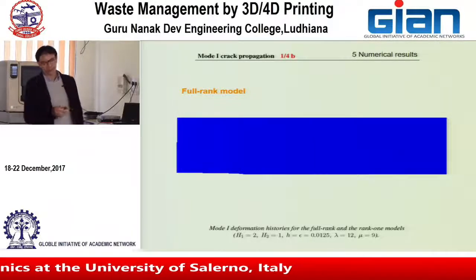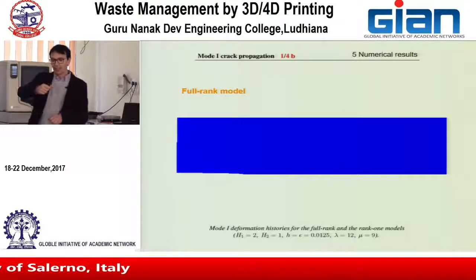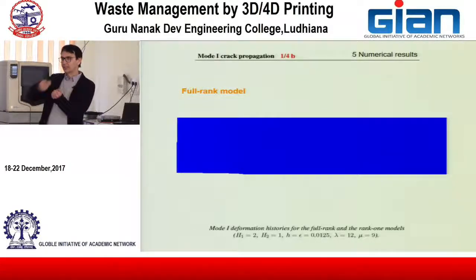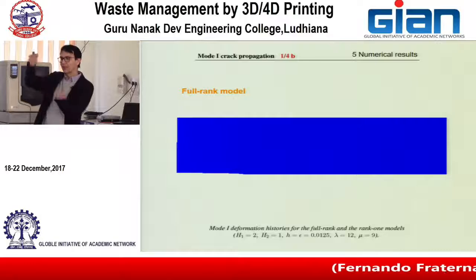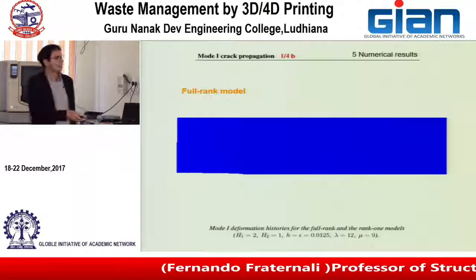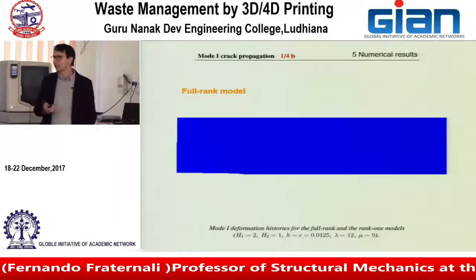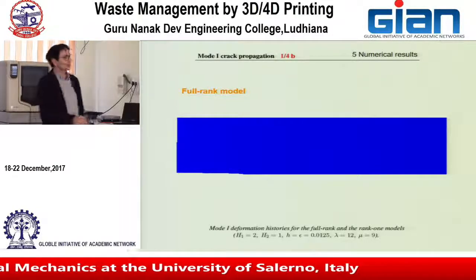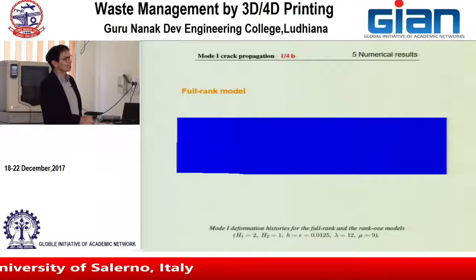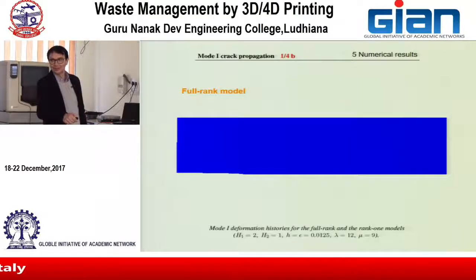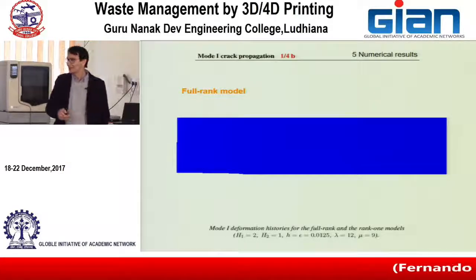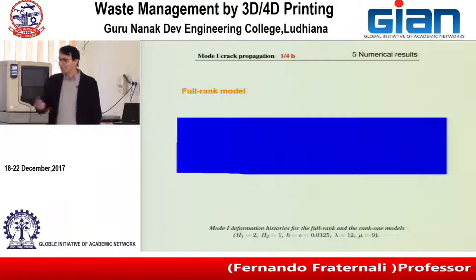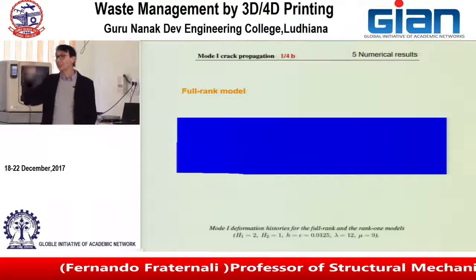So this is the case of a beam with an original pre-crack. This is pretty easy. Where do you search for the cracked element in this case? Near the initial crack, in this region here, no? You try to crack this element, and you see if it is convenient or not, so if the total energy decreases or not.